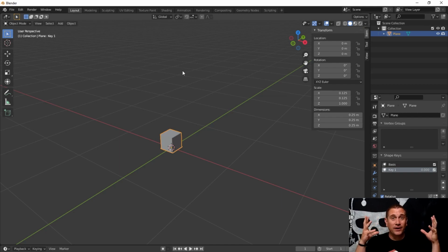Is that kind of crazy? A UV map, if you're not familiar with what it is, is telling the 3D object how a two-dimensional picture gets wrapped around it, like a texture, how it gets wrapped around the 3D object. You can have control over that. You can map something top down and wrap it around from the top or from the side or from the bottom. You can choose how an image is wrapped around a 3D object. And that's the art of creating UV maps. And we're going to do 3 of those.